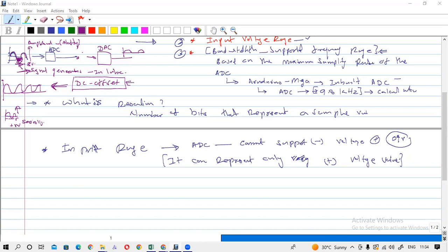So you can give a DC offset. Actually, you need not use the DC offset if you have a power supply. If you connect 5 or 6 volt serially with the signal generator, you can shift the signal again. There are many ways to give a DC shift.